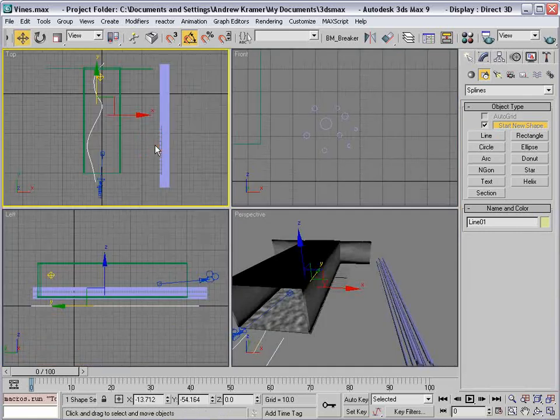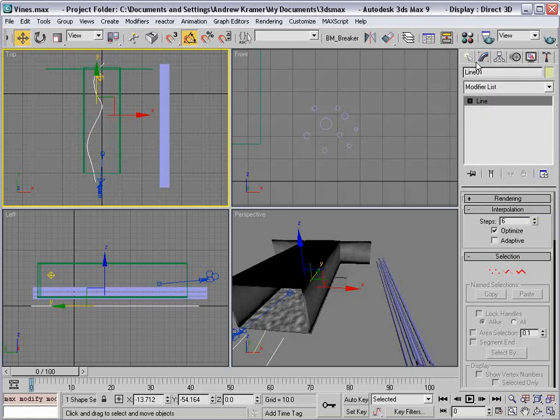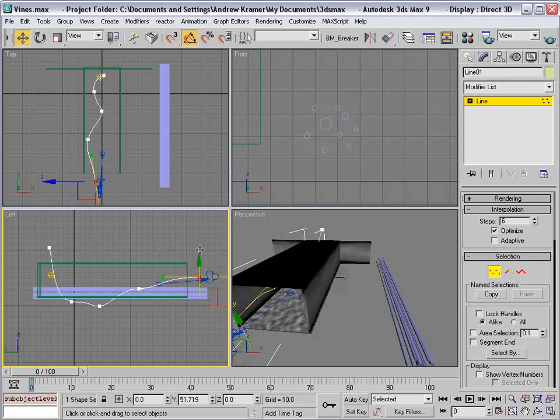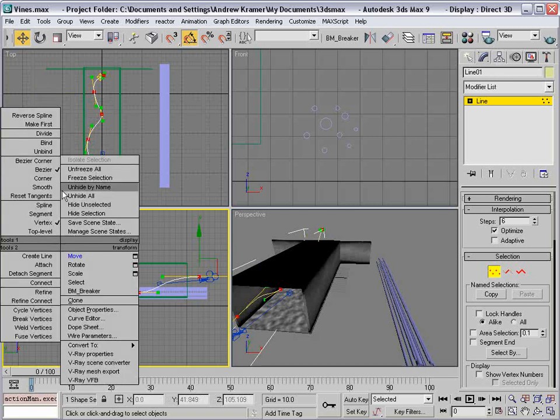I'm going to kind of make some adjustments to the vertexes. So take my line, go into the edit, and here we have our vertexes. Select that, and then we can grab one of them and just move it up. Grab another, move it up a little bit, and then our last one, remember we want this to kind of go out the ceiling and the top. So we can move these over to do that. Our begin one can start from up high. And we'll bring this one down actually, and then bring this one up higher. What I'll actually do is just select everything, right click on one of them, and choose smooth.